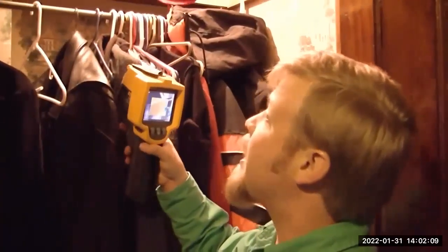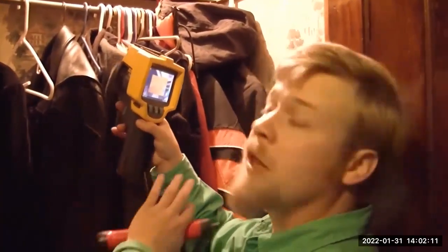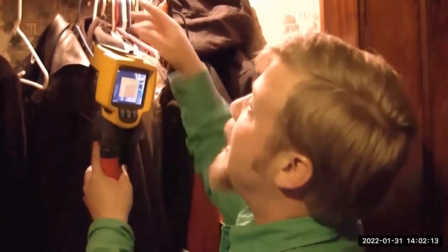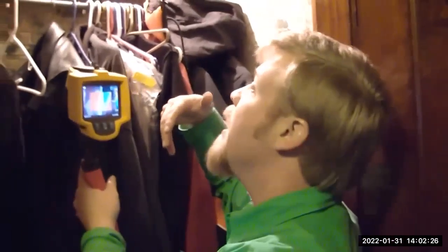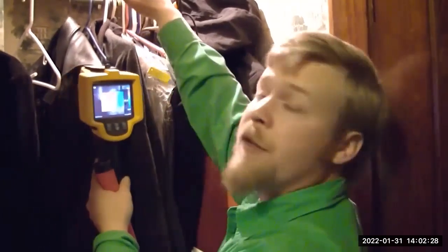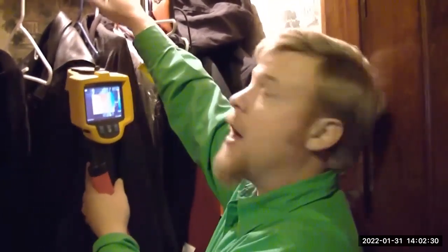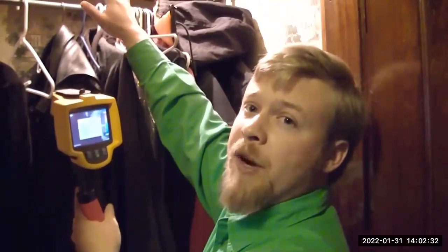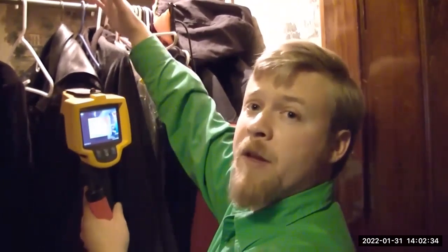Now, again, we're on the second story, and as I'm scanning this closet space in here, I find there's a lot of cracks in the plaster through here. And if I shoot it with my thermal camera, I'm getting some real cold temperatures coming out through there. We can actually feel a draft coming through this closet itself. So what we need to do here is seal those cracks up to prevent all that air infiltration coming into the conditioned living space.